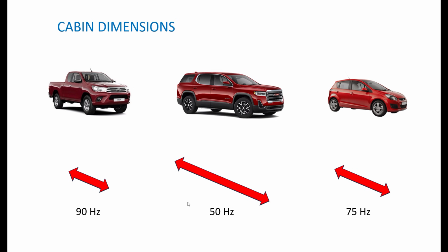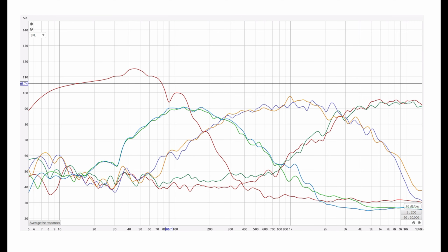Now how does this kind of show up? Well, classically, when we're doing our subwoofer RTAs, often you'll find we've got a great big dip somewhere in the subwoofer response, somewhere between, I don't know, 50 and 100 hertz. And often this will be a cancellation caused by a standing wave, right?